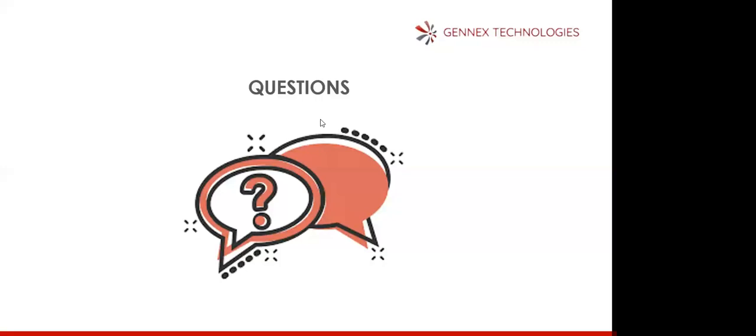If you choose a flooded battery type, or an AGM battery type, or a lithium battery type, either Weco, Pylontech, or other type of battery on program 5, it's a preset on its own, so you can't tamper with it. But if you choose user defined, you can set all those parameters on program 27, 28, and 29. Thank you.